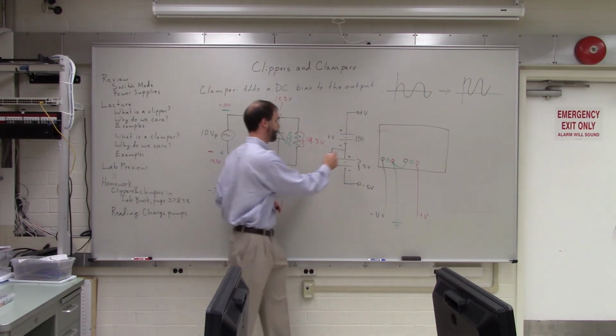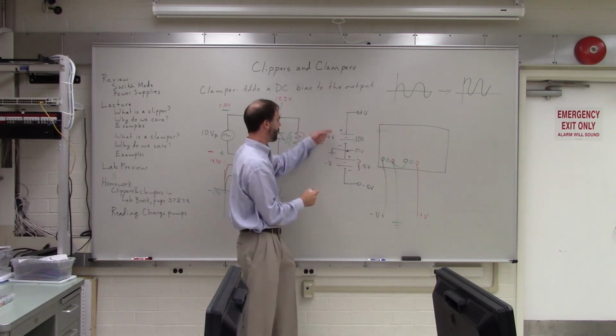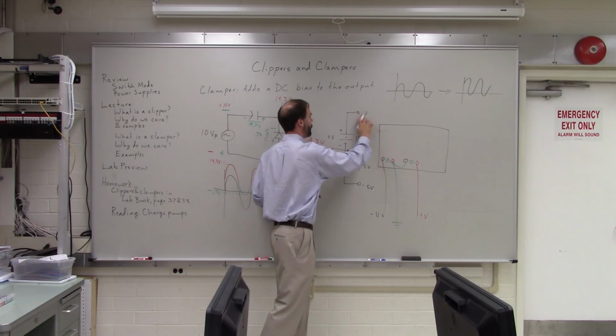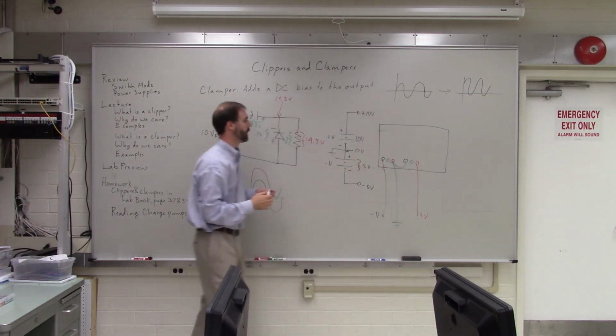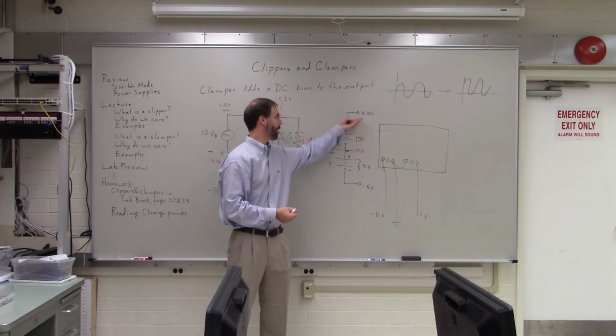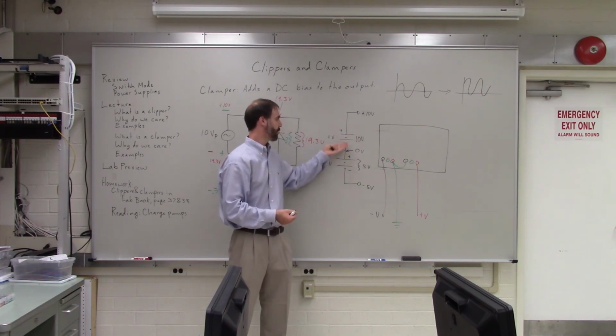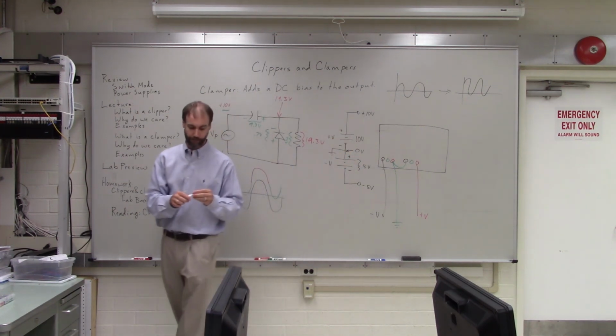You start at 0 volts right in the middle. You go up by 10. So what is your output voltage? Yeah. So that's how you can create a negative supply and a positive supply out of two parallel supplies in series. Okay.